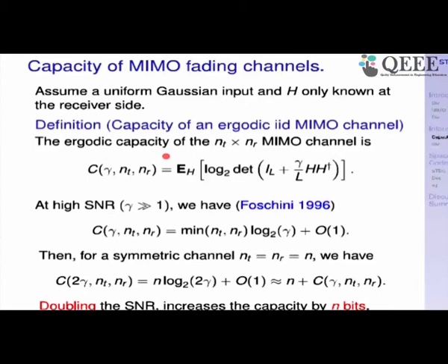PCP, I have already answered your question: how is channel state information generally derived at the transmitter. Typically, before transmitting the bits, the transmitter transmits a pilot signal. Based on that, the channel is estimated at the receiver, quantized and sent back to the transmitter side over a separate channel called a control channel. So it requires an extra effort. It is not always feasible, but current LTE etc. does have the feedback provision. So it is practical. Yes, any other questions?